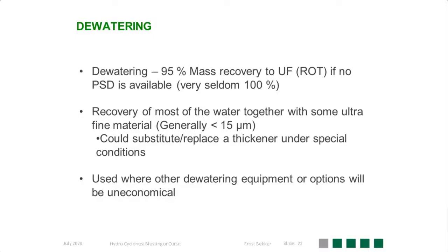It's not always possible. In some cases, the hydrocyclone can be used to replace thickeners, but those are very special applications, and in general, the thickener remains the best dewatering device in a process. The hydrocyclone can help with the thickener dewatering process, but it cannot always replace a thickener in the process.